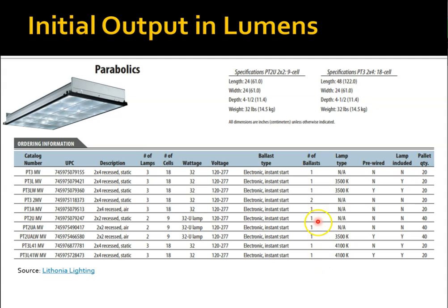The number of ballasts is actually fairly important because ballast costs money, and also ballasts are equipment that can fail. So if possible, it's nice to have a limited number of ballasts, but there are also other considerations. I mean, everything's complicated, I'm telling you. We can have multiple ballasts within a single luminaire, right? So if we have 4 lamps in here and 2 ballasts, then that will enable us to turn half the lights on and half the lights off because we have separate ballasts.